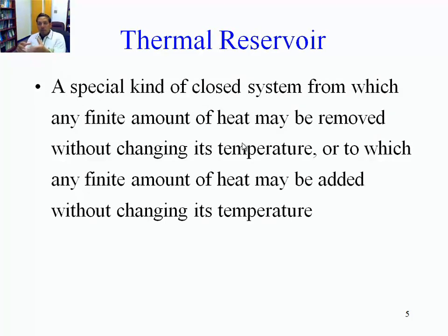In order to define those consequences, let's define what a thermal reservoir is. A thermal reservoir is a special kind of closed system from which any finite amount of heat may be removed without changing its temperature, or to which any finite amount of heat can be added without changing its temperature. So think of a thermal reservoir as something at a constant temperature, but so big that you can add as much heat as you want, a finite amount, and the temperature will not be affected. Or you can subtract the amount of heat that you want, and its temperature won't be affected.